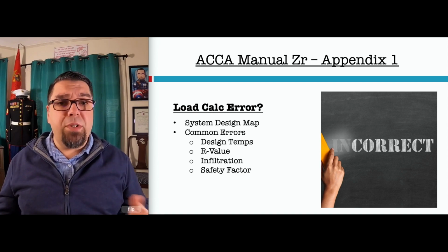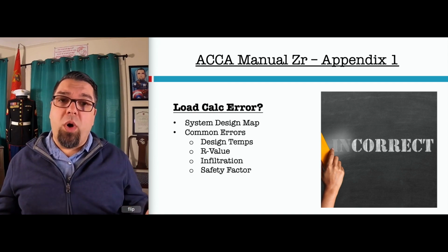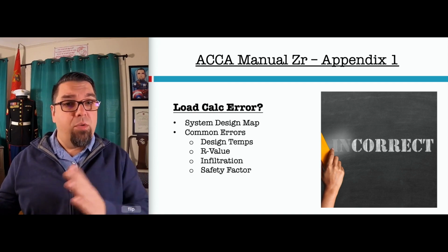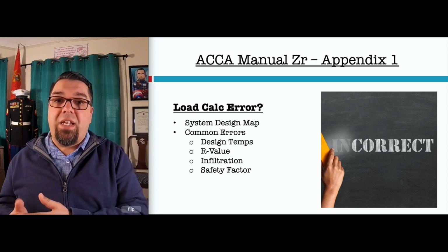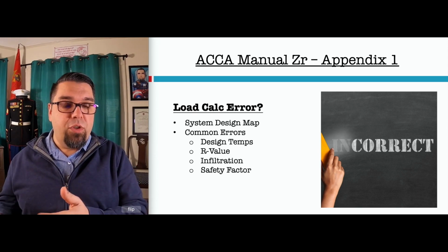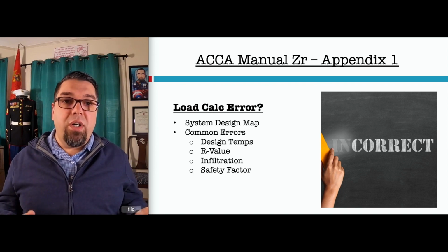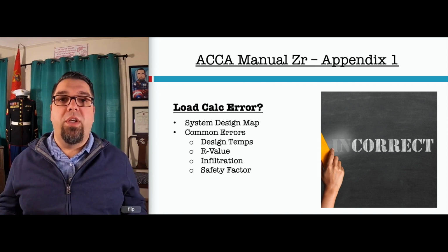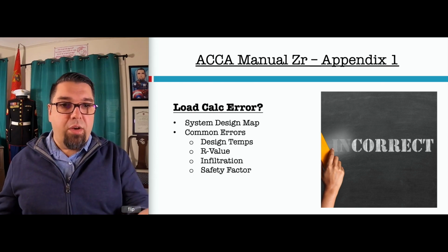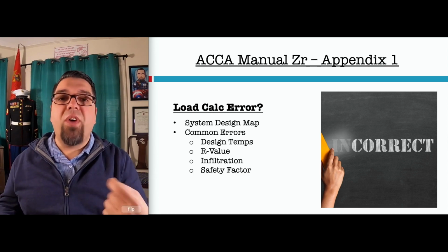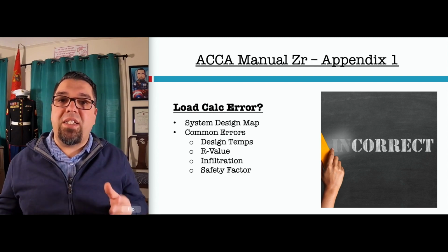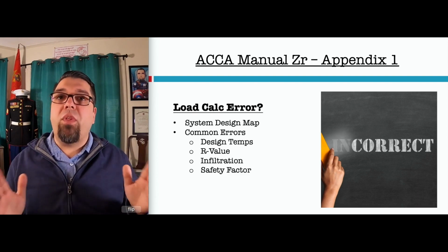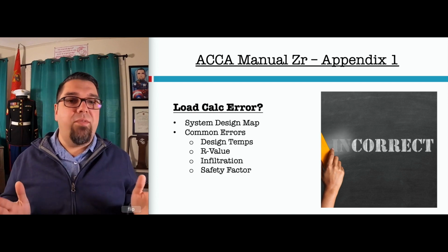So design temperature is the number one thing. Obviously Table 1A, you're gonna make sure you match your outdoor design conditions based on the 99% or 1% design temperatures for your location. And then indoor, it's defined by the International Residential Code and is part of building code. Obviously, if you don't know what those are, there's many resources here. I'm just going to rattle them off for you though. In heat, it's 70 degrees plus or minus 2 is the only leeway. Low is 68, high is 72 inside.